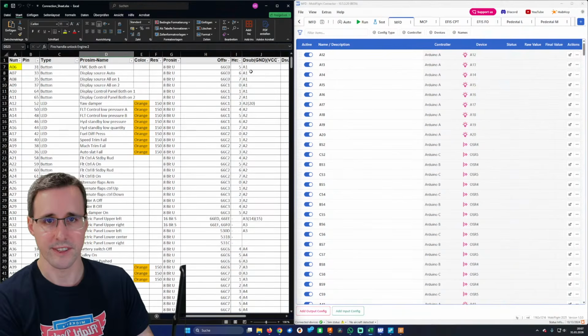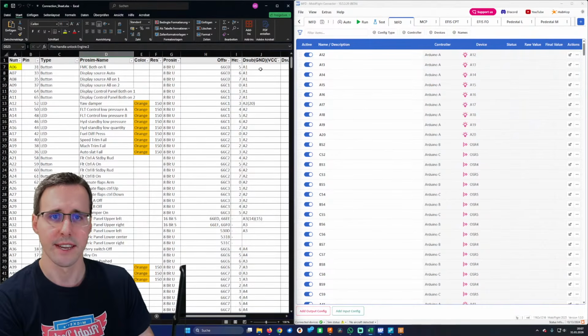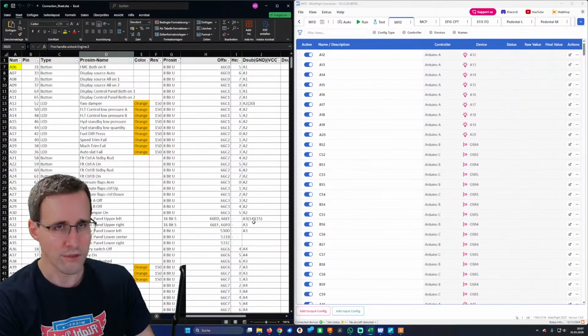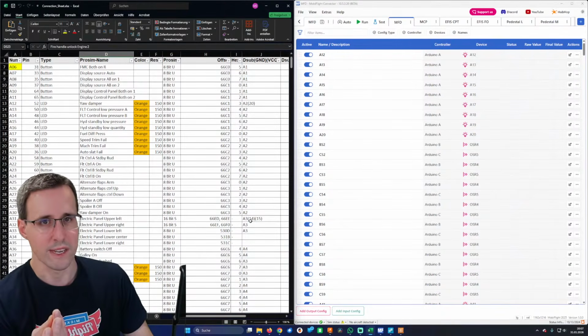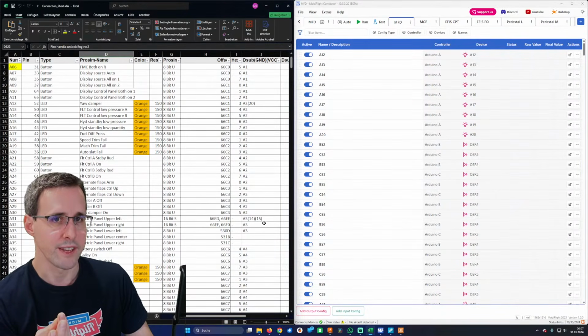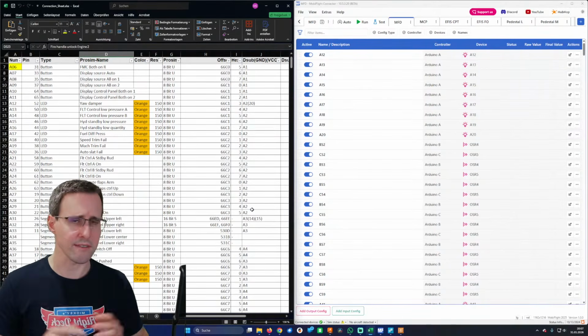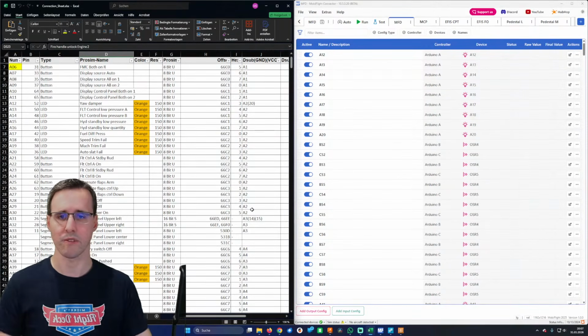This is a D-sub connector A1 or A2, A3, and so on. Also it is documented which are the ground and the voltage connections. So on pin 14 of this connector, we have ground, and on pin 15, there is the 5-volt cable connected. So this is just hardware stuff, cabling and so on.